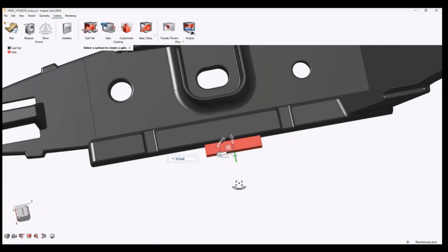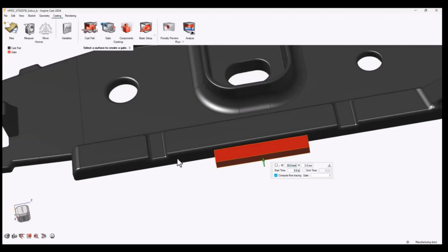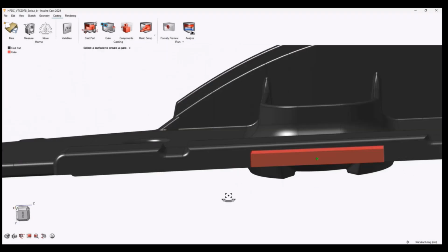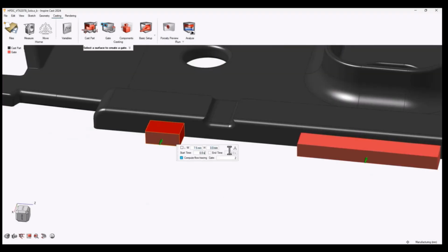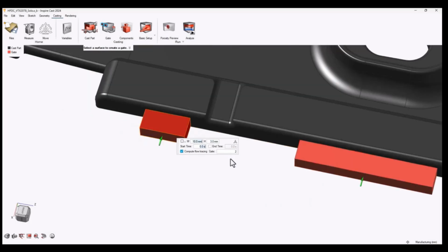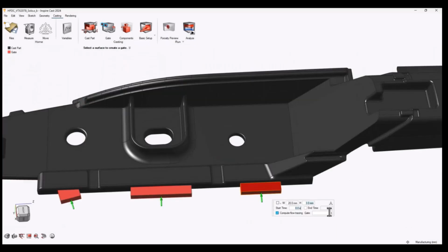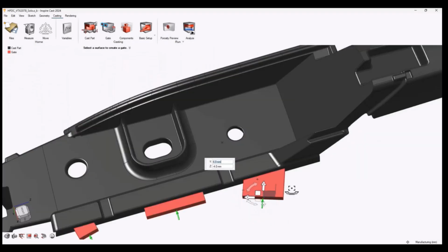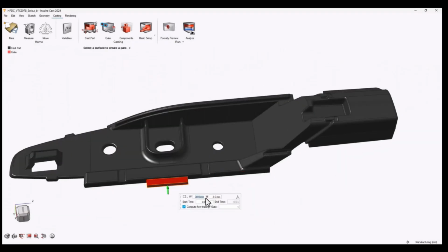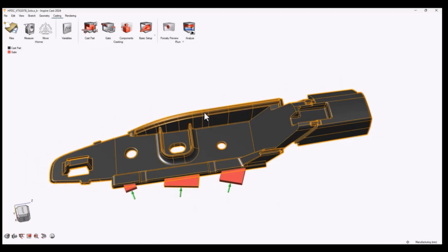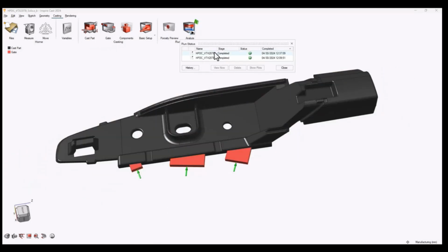Now as you see, there were certain errors when he was filling it. The molten liquid is cooling at a faster rate. So he's trying to increase the ingates. So you can provide multiple ingates for your molten metal to move inside. And also you can provide different orientations for the entry flow.